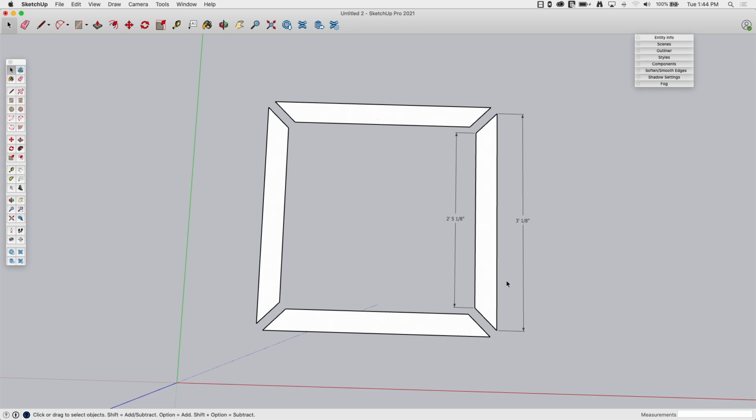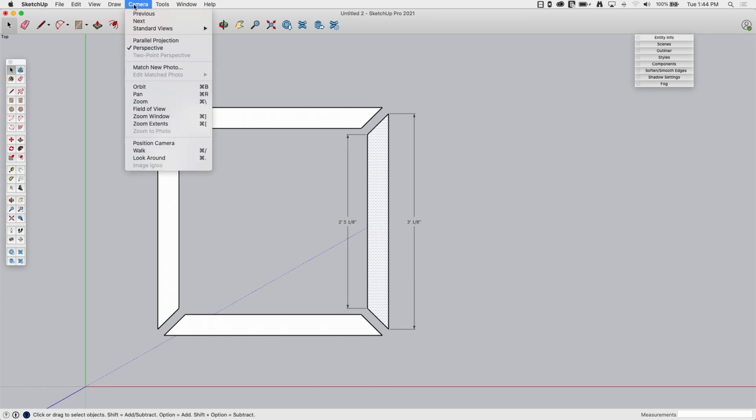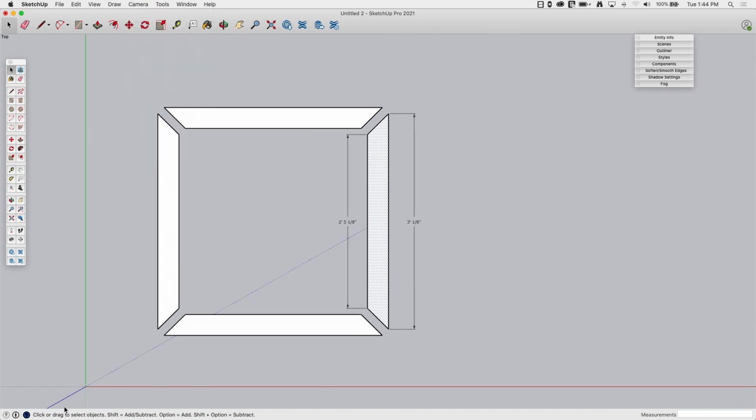So if that's the case, to export this is something I would just do from SketchUp. I have access to LayOut. I've had it for years and years, but there's still plenty of times where I take a simple reference image like this and just print it right from SketchUp. So here's a couple things to note. One thing is wherever possible, I try to get it flat to the screen. So one thing I'll do is click on a surface and hit Align View. That's going to assure that I'm looking straight down. Because I drew this in 2D, it's flat. It's not going to matter too much if I switch between parallel projection and perspective.